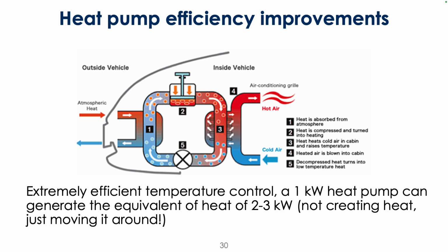So the heat energy that you get compared to your energy input is actually higher than that energy input. A 1 kilowatt heat pump can generate the equivalent of 2 to 3 kilowatts of heat, and that energy is coming out of the ambient air.